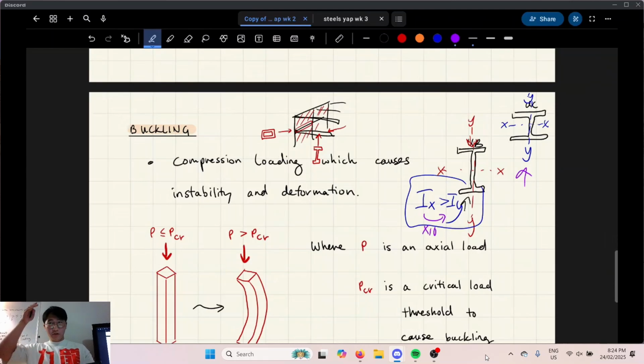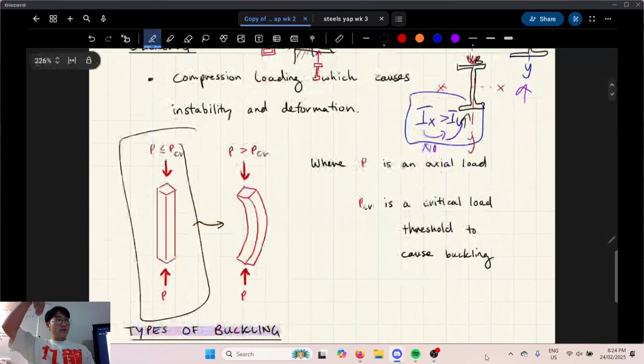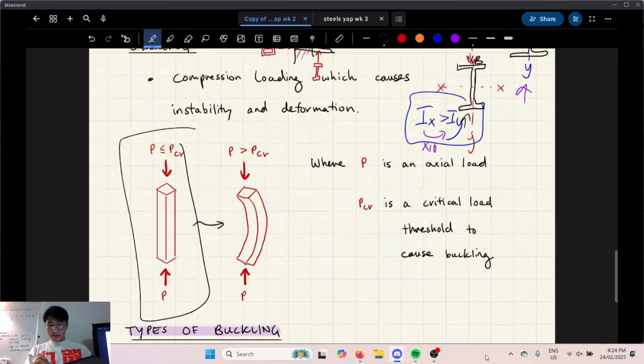When you orientate these columns vertically and they're taking on axial loads, essentially you have to check buckling in both directions, because bending can happen in both those directions. It's not a matter of gravity load. Gravity loads are just acting like this, but then they can buckle in the x direction or y direction. But there's always a stronger axis, unless it's a square hollow section, which sometimes is the case.